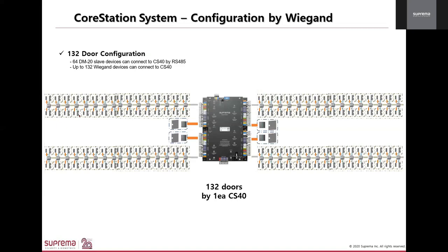So don't confuse the two. When you have RS-485 and Wiegand, they're 2 different communications. So be very wary of that as well. But you're not stuck to one type. You can mix and match in the system. You could have RS-485 and you can have Wiegand connection, but then also keep the limitation in mind by going that route.